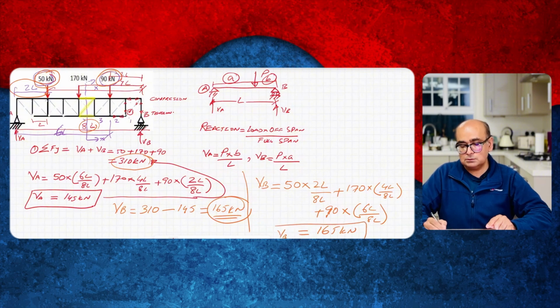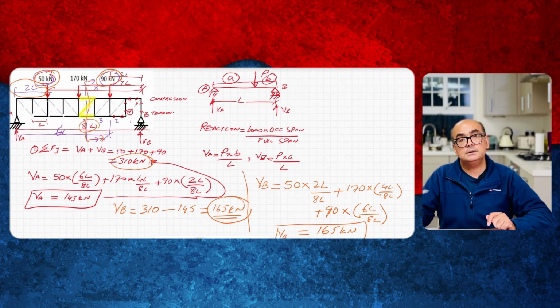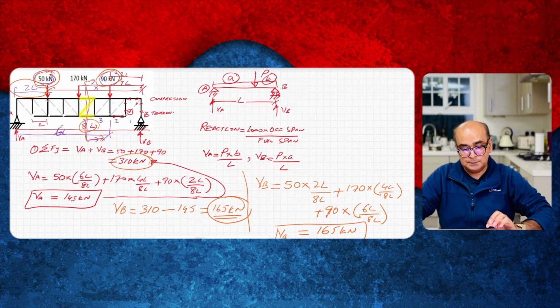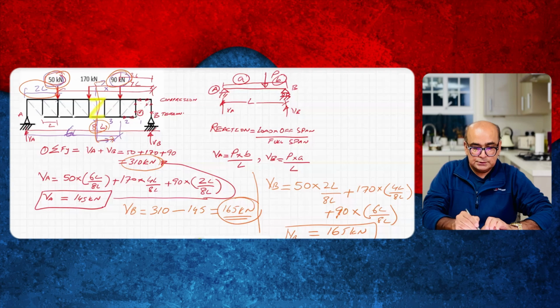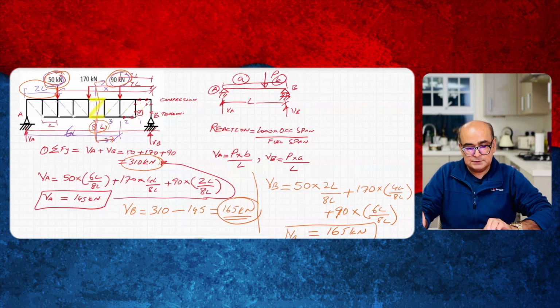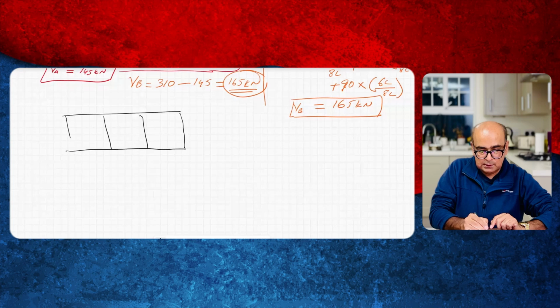The first step is always to find out reactions, and then we can figure out where the maximum load is. And in our case, it will pass through this XX section. It will be in top chord or diagonal or bottom chord, but the chances are that it will be in top or bottom chord. So let us take this section and then take the moments. We have 1, 2, 3, 3.5 spans. Let's draw this out. So I have 1, 2, 3 and 3.5 span.